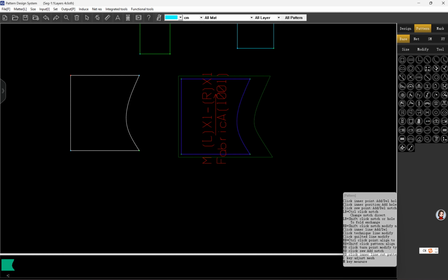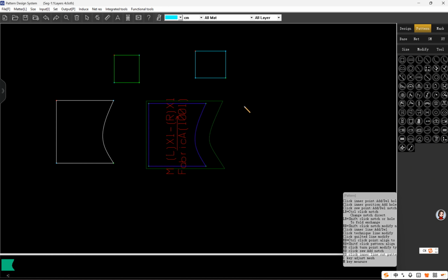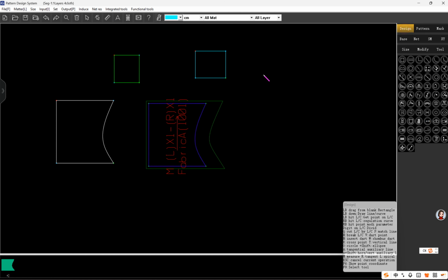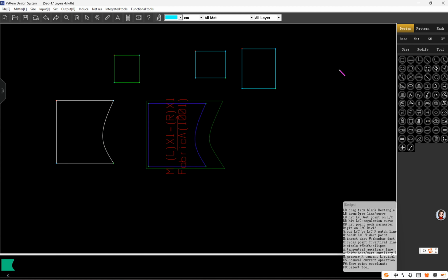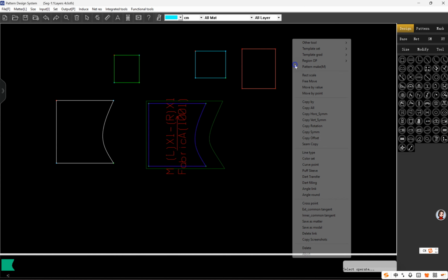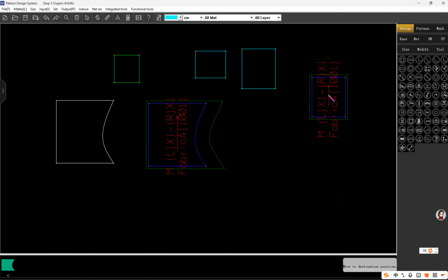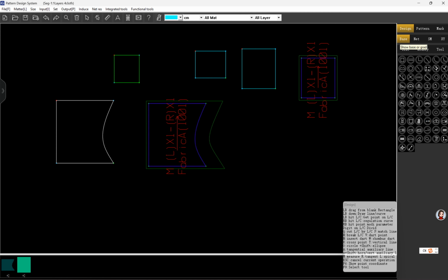This is the base size and the grid. If we make a pattern with grading, pattern design, and make a grading here, right click, press Alt and G, we can check the grading. And also, when we generate patterns, we can switch between base size and the mesh diagram.